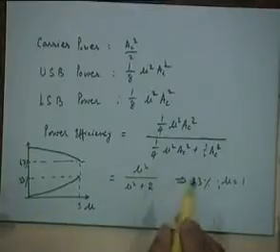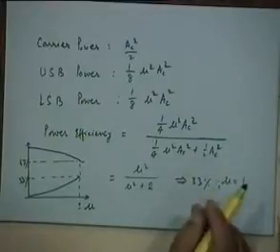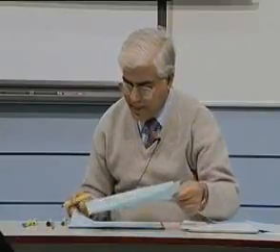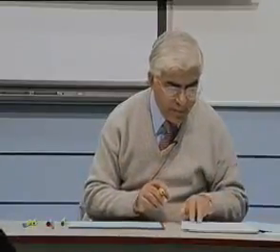This discussion we have carried out when the modulating signal was a pure sine wave, right? One can prove that for more general kinds of modulating waveforms, the power efficiency can be increased, but under no circumstances will it be more than 50%, like we discussed earlier.